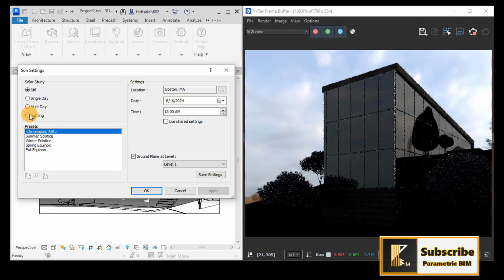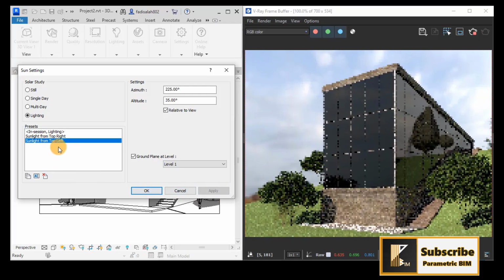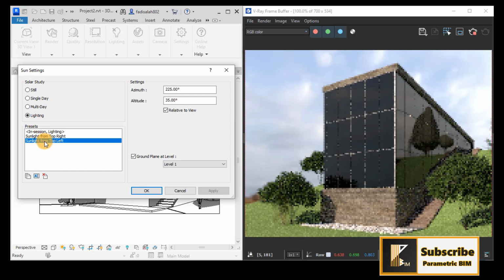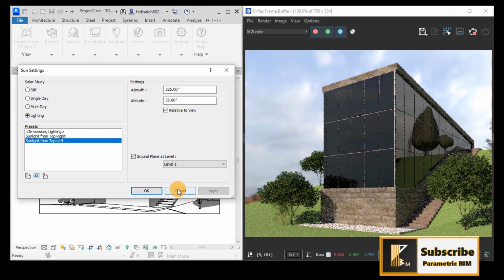So the critical point is that the sun settings here in the V-Ray are related to the sun setting in Revit. Let's change that to this one, which is lighting sunlight from top left and related to azimuth and altitude. So this is the first lighting source, or the first lighting type in V-Ray.